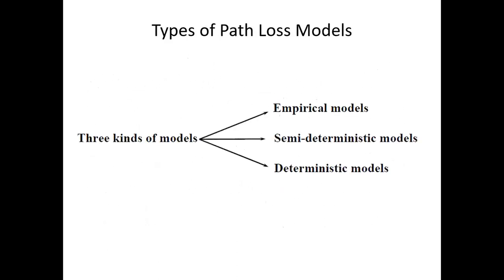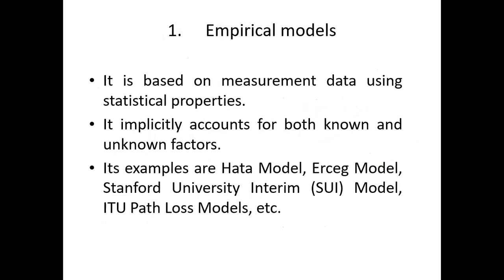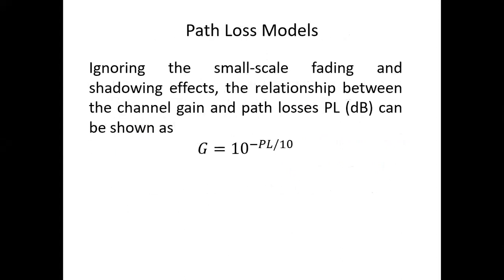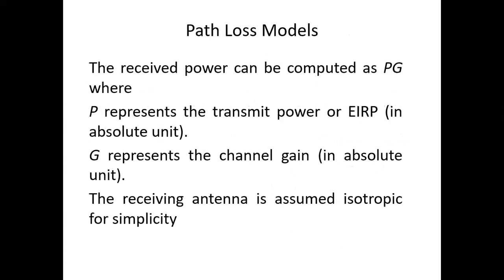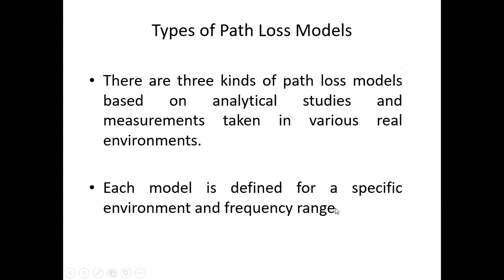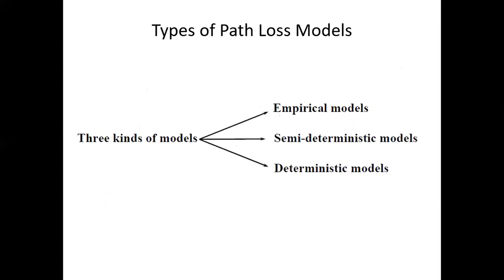These models' purpose is just to show you how much loss of the signal you have on the way, so you call them path loss models. Also, you can write it in a way that gives you directly the received power. Basically from PT GT GR, you are subtracting the path loss, or you may put them this way, just multiply P with G. So either you show the received power or you show the PL in the representation of a particular path loss model.